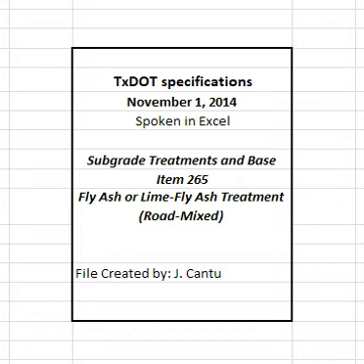When treating with LFA, apply, mix, and mellow lime first unless otherwise directed. Start treatment operations only when the air temperature is at least 35 degrees Fahrenheit and rising or is at least 40 degrees Fahrenheit. Cease operations if the 24-hour projected air temperature is less than 32 degrees Fahrenheit for more than 4 hours. The temperature will be taken in the shade and away from artificial heat.